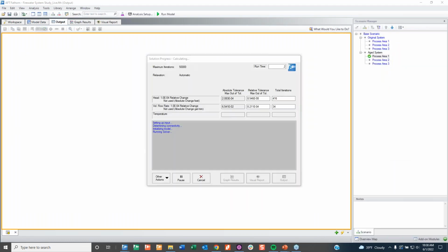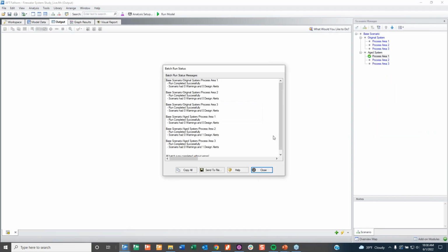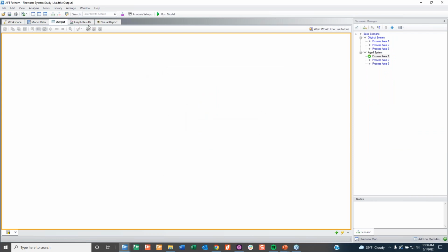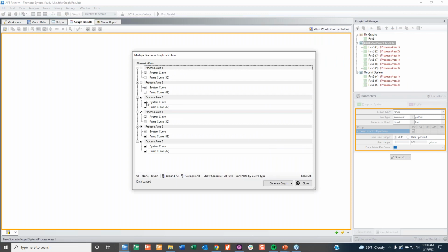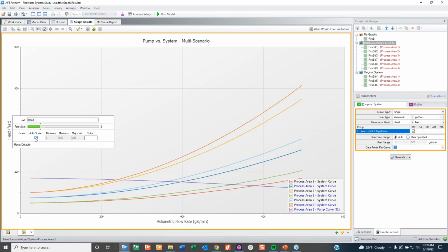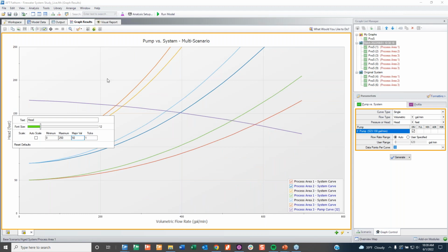The reason it takes a little bit of time to generate a curve, you can probably see it picking up here, is because the model itself is at one flow rate. It kind of has to do this theoretical, like, let's see, it's the same pump. Sorry, I'll get back to my explanation here. So I'm just showing different system curves because it's the same pump. Okay, and I'm going to change this to 50 and 50, just a little formatting thing. The model itself is at one flow rate, right? But to get a system curve, Fathom has to do this theoretical. What if it was at 0 flow and so on. So it takes a little bit of time.